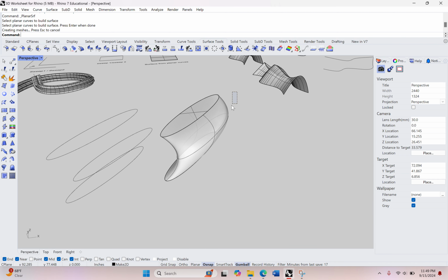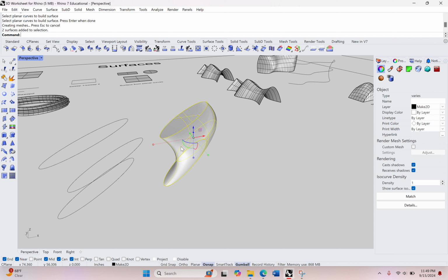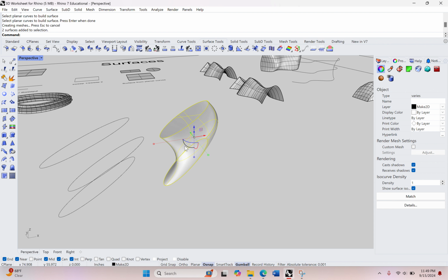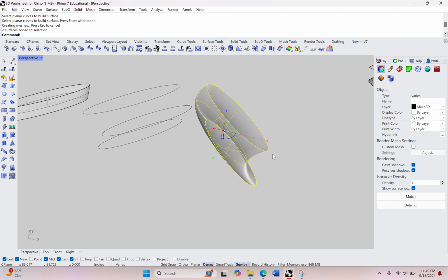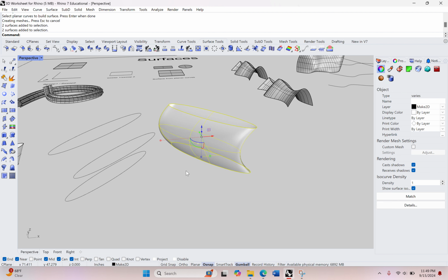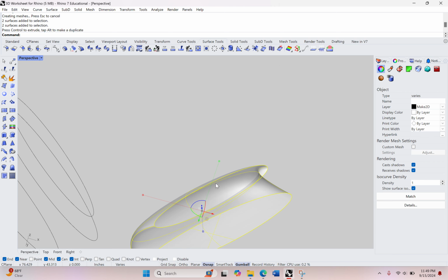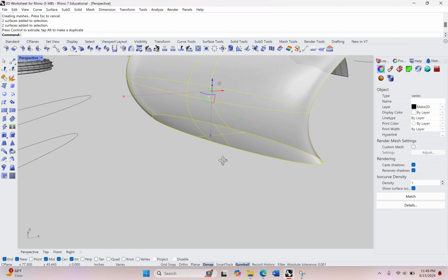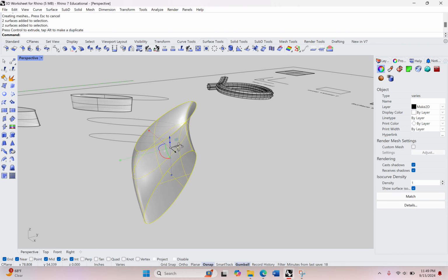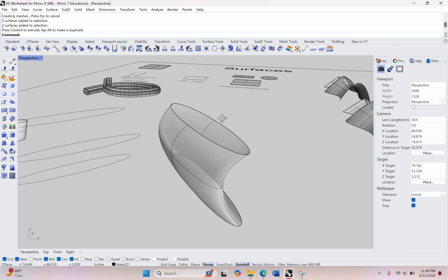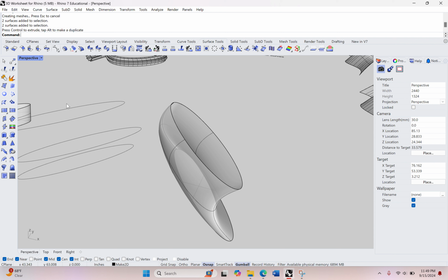Now let's select from right to left. That way we can grab this whole structure so far. And on the green curved line on the gumball, really you could use the green or the red, either are fine. I'm going to rotate it 180 degrees to tip it upside down. I just like to do that. I don't like to rotate my viewport camera to get underneath because it feels a little strange to me doing it that way. I like to pretend like I'm working on a desk. That just makes it more simple for me to do this.